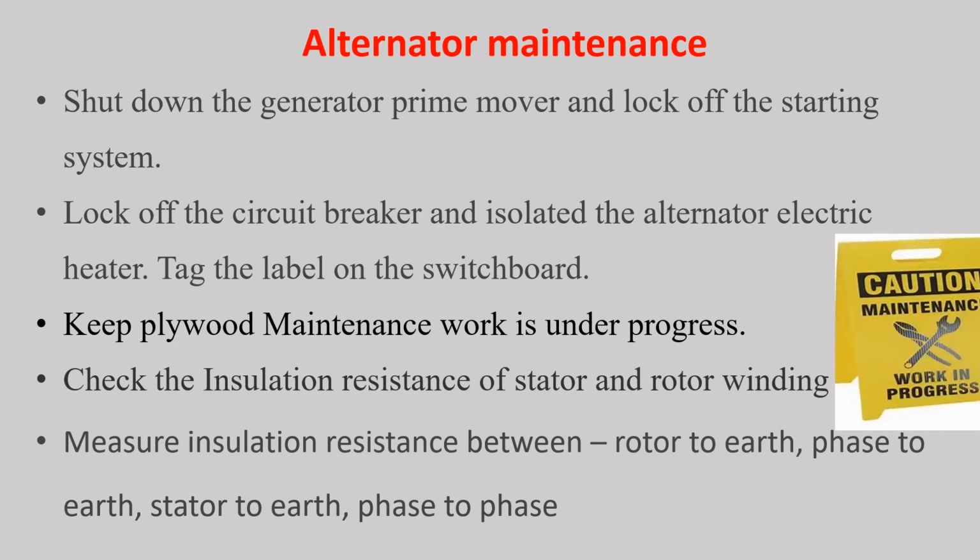The Megger is used to measure the insulation resistance (IR) value. If insulation is very low, it may get heated up, get burnt, and catch fire. The lifespan of the windings will end soon. So it is very important to check the insulation resistance.